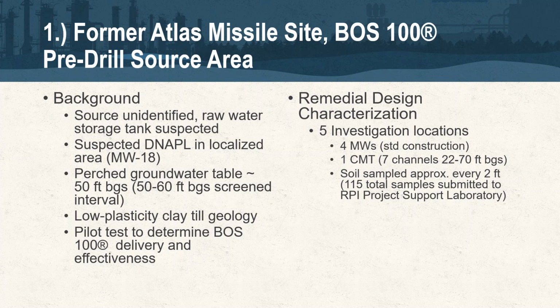And so this was a pilot test to be able to see if the BOSS 100 technology could handle these concentrations and also get distributed in the subsurface. There was a perched groundwater table at around 50 feet BGS. It was a low plasticity clay till that we were injecting into, and this actually was a pre-drill site.